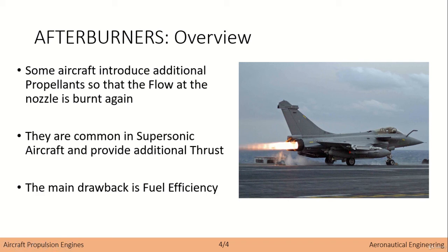These afterburners are quite usual in supersonic aircraft, and what they do is provide additional thrust. However, the main drawback is fuel efficiency, because you're basically burning more fuel in order to get a bit more thrust. In general terms, you won't find this in commercial aircraft.